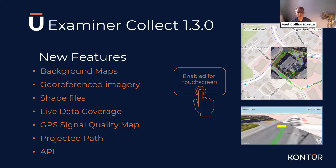You have live data coverage, so you're seeing where you've driven, what you're collecting, where you're overlapping, for instance. You talked about, can you see the radar coming in? Yes, you can. You can see all three views of the data coming in with the horizontal cut as well. These are new features in addition to the ones that we already have. You also see a GPS signal quality map, so you see the fix. So not only where you've been driving, but also you can switch to a color map that shows you the quality of the fix information that's been coming in. So if you have poor fix somewhere, you can do something. You can see where the GNSS quality has dropped.